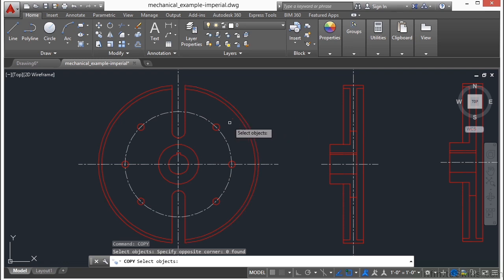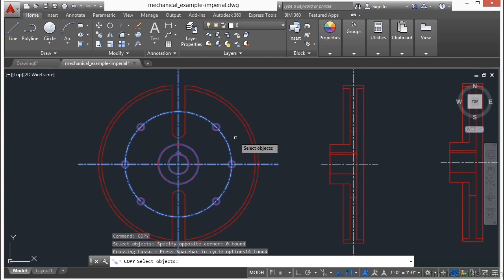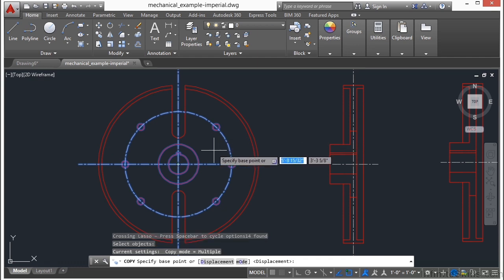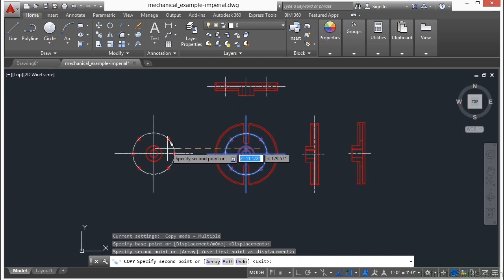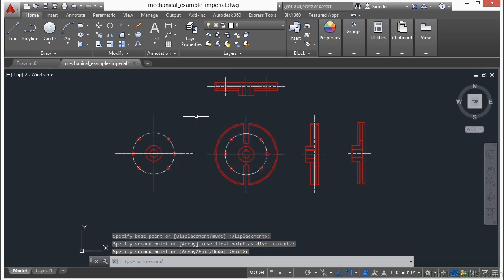That'll end that selection. But this time what I'm going to do is I'm going to left click and hold. I'm not going to let go of it. I'm still holding it down and I'm moving my mouse. Everywhere I move my mouse creates a selection window, but it's like a polygon here. It's a weird amoeba shape, and it's only going to get the items that I select inside there. Then I let go, and just those items are selected. Press return, pick a point, zoom out, and there, press return, right click, and press enter to cancel out of there. So you can see here, I have these different options.